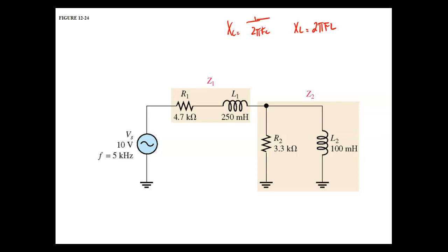So on series circuits, since current is constant, voltage in capacitors lags, but over here leads. So leading would go this way, lagging would go that way. If you get these guys in the same series circuit, that's where it really gets weird. You might have these guys right here dropping the applied voltage.